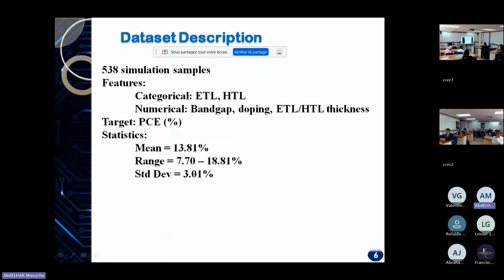From the simulation, we built a dataset with 538 entries. Each sample corresponds to a unique device configuration. The dataset includes categorical features like the choice of ETL and HTL, and numerical features such as band gap, doping levels, and layer thicknesses. The output we focus on is the power conversion efficiency, with an average of about 13.8%, and values ranging between 7.7% and 18.8%.